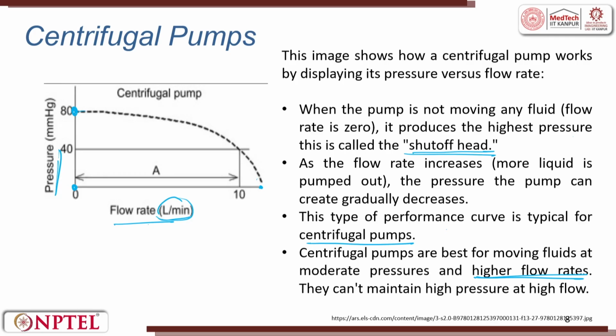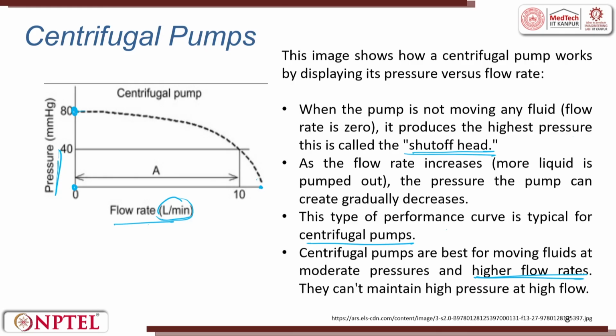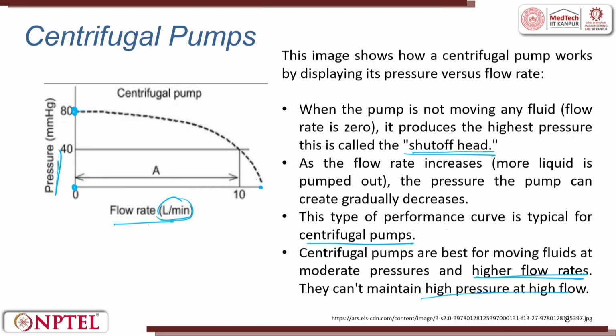In agricultural applications, we try to have moderate pressure and we need very high flow rate, because the water has to be sucked from the well and it has to be dispersed, right. They cannot maintain high pressure at high flow. And for agricultural applications, you don't need the tight requirements. So, friends, this will try to tell you where and when to choose centrifugal pumps.